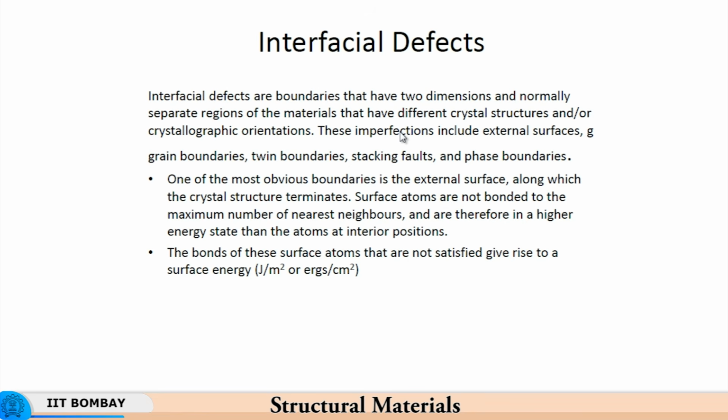So you have these grain boundaries where you do not have any orderly arrangement of atoms, so the atoms are randomly arranged. Naturally they would not occupy the positions of minimum energy, and hence the grain boundaries are the regions of higher energy content.